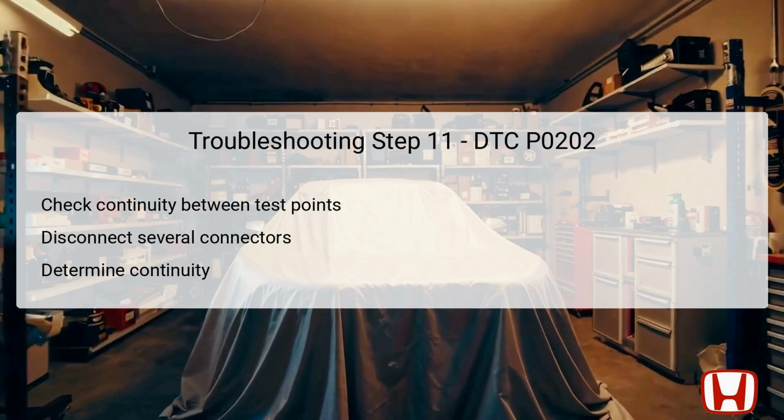Reconnect the injector control module connector D4P if it was previously disconnected. You will also need to jump the SCS line using the HDS and allow a minute of wait time for the actions to take effect. Next, disconnect both the injector control module connector C12P and PCM connector B51P.